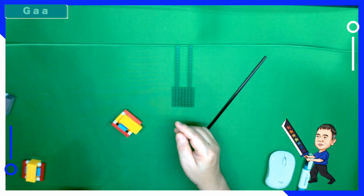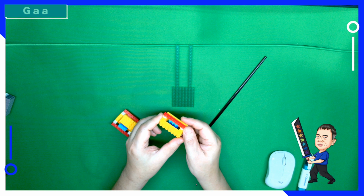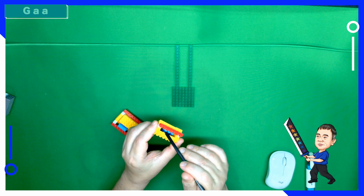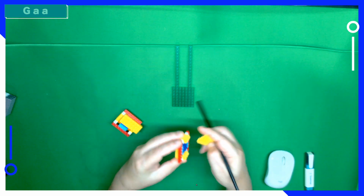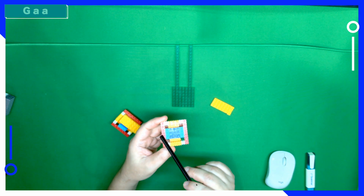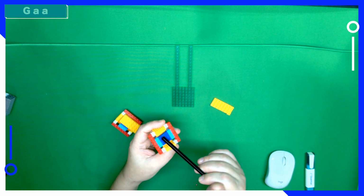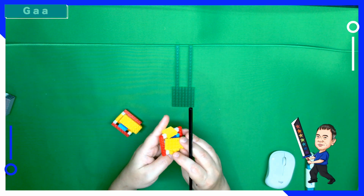Now if I take the oxide part away, it's going to look like this. You can see the gate totally surrounding the channel. Now the channel, if I take the top and bottom away, you can see it looks like a bridge between the source and the drain. And it also looks like a sheet, S-H-E-E-T. It looks like a bridge, B-R-I-D-G-E, and it looks like a sheet. So sometimes we call it a bridge.